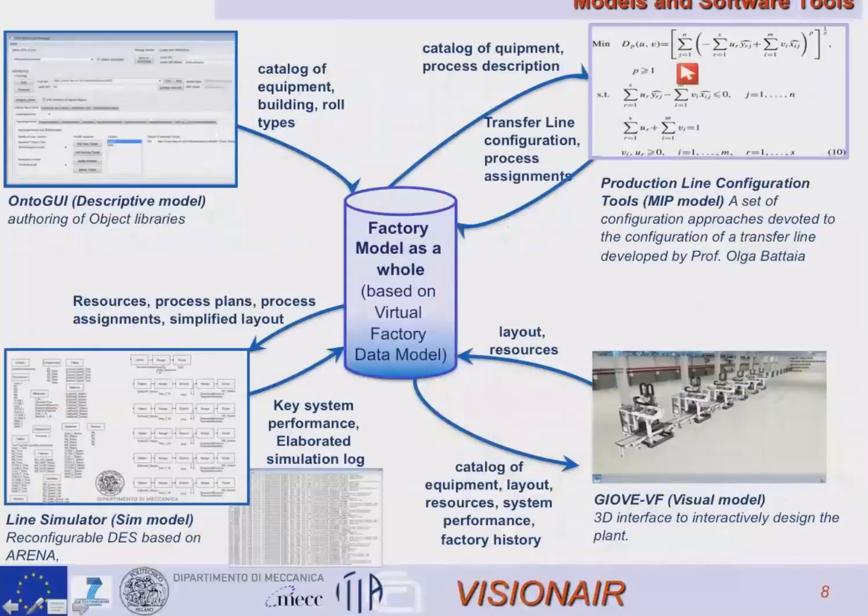And so, as I said before, we use an ontology graphical user interface to insert the data related to the process, the different manufacturing operations, the processing time, the machining direction for all the machining work steps. And we use Arena simulation. In particular, we use a piece of software that is able to drive Arena to simulate what is inside the ontology, and this was developed by Politecnico di Milano.